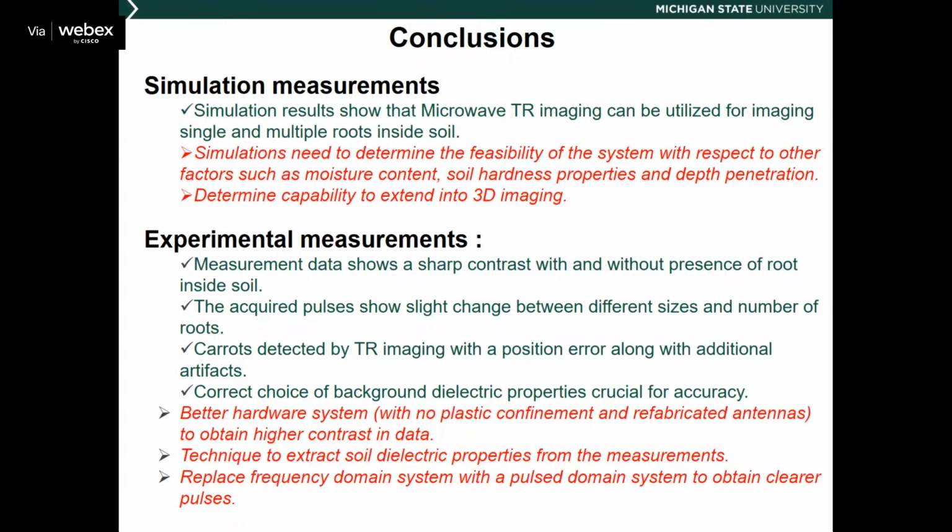So one thing that we want is to design a microwave sensor which will have a broad frequency range. So this is one thing that we figured out. A narrow band will not work very well in this case, unless you know exactly what you're trying to image. In this case, you have a very complex composition of the material with different types of soil and roots. So we realized that a short pulse in time domain, wideband in frequency domain, is what we should focus on.